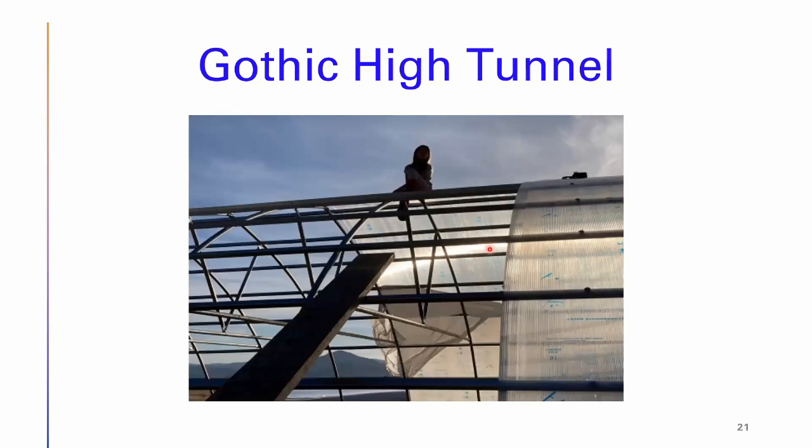So this is that kit. We built that a couple years ago. As you can see, the glazing, this is 8mm 4-layer glazing. And these are 7-foot wide, well, 6.9-foot wide panels. I'll explain how the nominal at 7 feet works shortly, but these are 19-foot long panels. So they fit right on your purlins, these horizontal members, and you screw them in with self-tapping screws.